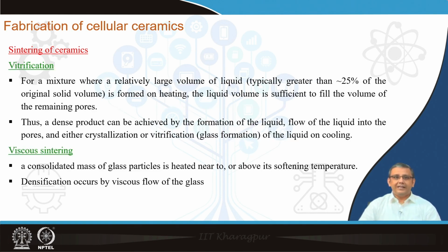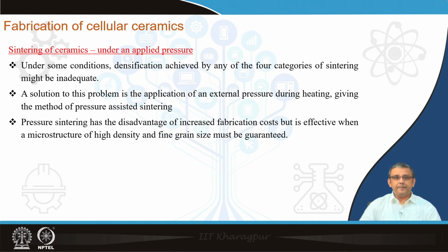There are also lesser established processes like vitrification and viscous sintering. But I reiterate that for porous ceramic fabrication, it is solid state sintering which is the most important process, and liquid phase sintering or vitrification is rarely performed for porous ceramic fabrication.